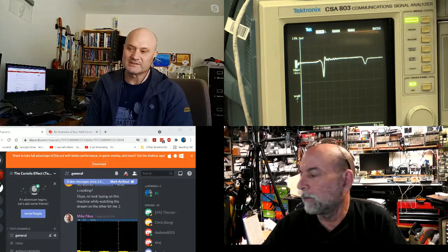The odd thing is, if you're talking digital electronics, we're talking very broad bandwidth signals, because you have a very high rise time pulse and then flat levels for some time. And with RF, you're dealing with a presumably sinusoidal carrier that may have something superimposed over it, or it's probably just a pure sinusoid that may be frequency modulated.